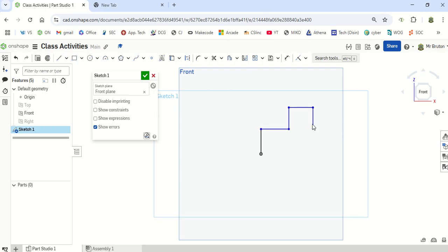Now, what I need to do here is make sure that this point here is locked in with that one. So I'll just show you how to do that last one again. So we need to find this point here. If it's not picking it up, you just move over to it and then move it over like that, and you can see that the dashed line there tells you that it's horizontally kept in line. Horizontal, vertical, horizontal, and again we want to get this last point here. Again, if it's not picking it up, just move your mouse over that point and it'll track it like so.